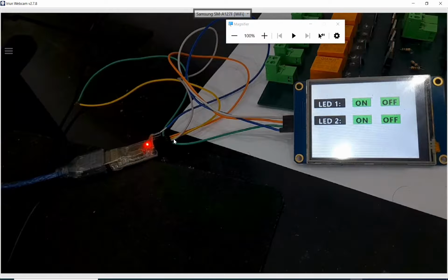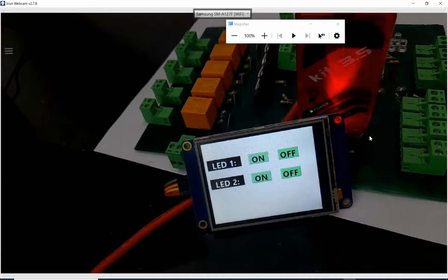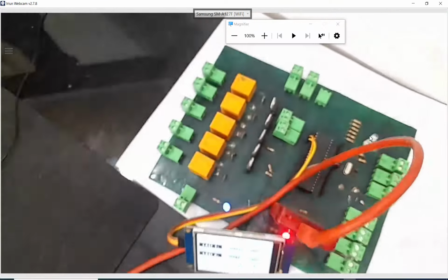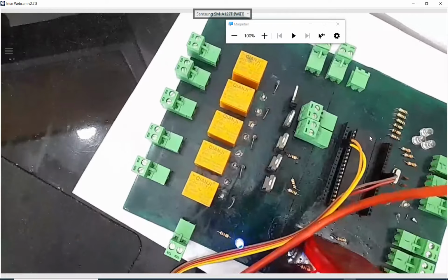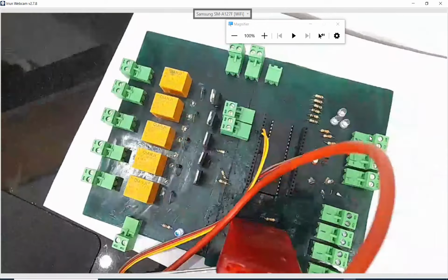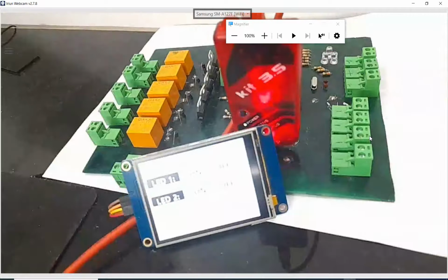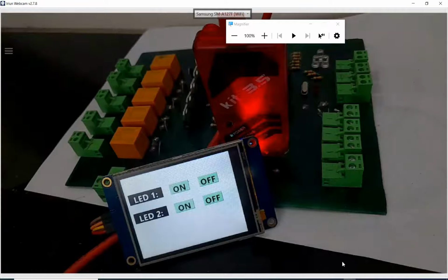Now we need to remove these wirings and connect it to the PIC as shown in the presentation. So let's do that. So guys, this is our hardware for the PIC. Now you can see that this is rewired as shown in the presentation. Now I have connected the PIC16F877A microcontroller. I'm using a 20 MHz crystal, and these are the LEDs which will turn on and off as required by our programming. So guys, before we continue, let me show you how to do the programming.